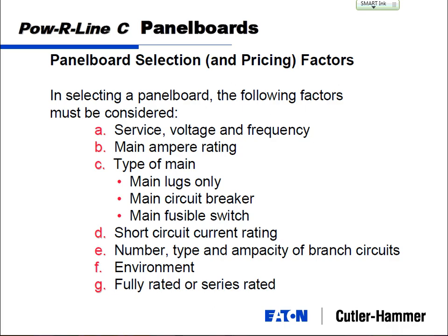The first thing I think about is safety. When you're changing that fuse, you've got 480 all around you. The second thing I'm going to say is availability. What happens if you don't have that fuse? It isn't there. You're down until you go to your local distributor or wherever you can get a fuse, and come back and put it in. So with those two primary factors, circuit breakers are really becoming predominant in the industry, except for special applications.